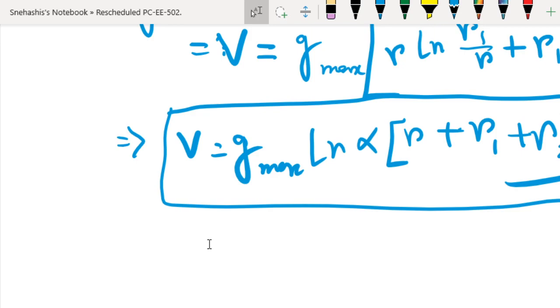Now, in case of intersheath, there is a possibility of damage of the intersheath during laying operation. That means when cables are buried underground, when cables are laid. And besides, the charging current flows through the intersheath also, which in case of a very long cable may result in overheating. So for these reasons, modern practice is to avoid grading in favor of oil and gas filled cables. So for gas and oil filled cables, grading is generally avoided.